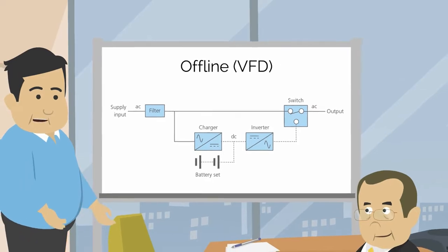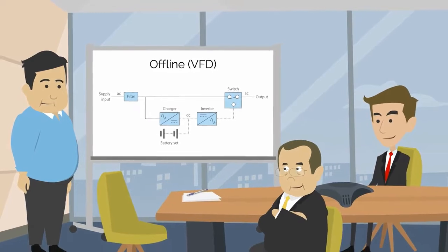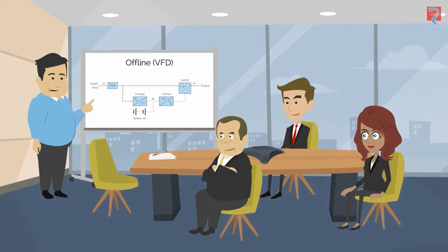Although this sounds a very short period of time, it is enough of a break in power for sensitive modern equipment to notice. Due to its design, an offline UPS does not protect against other mains-borne disturbances. Therefore, this type should only be used for non-critical equipment.